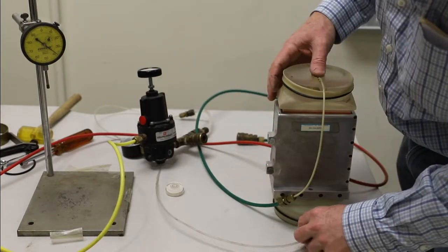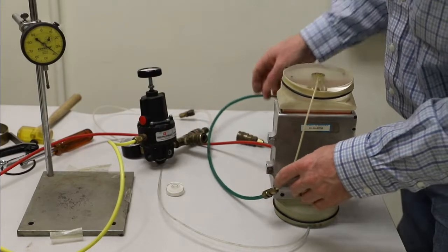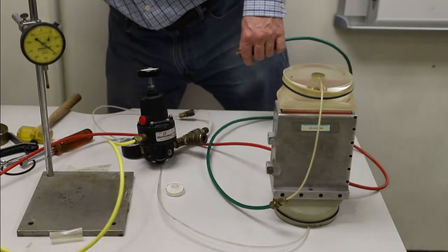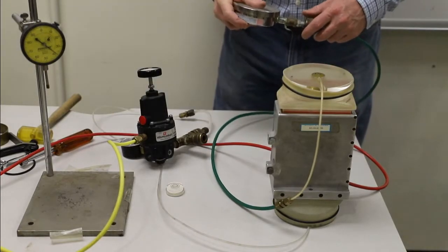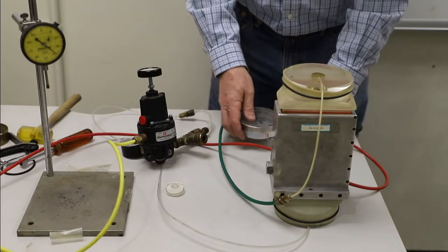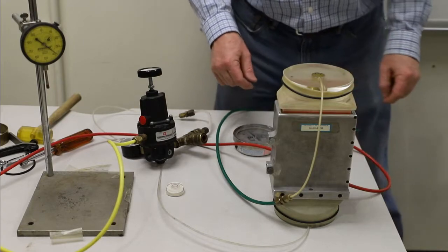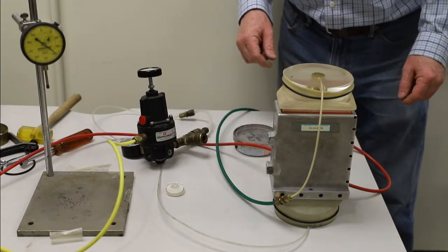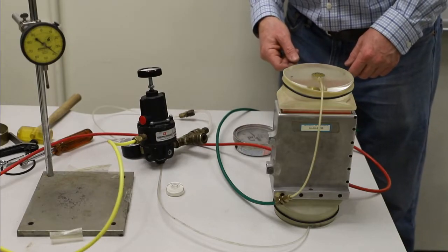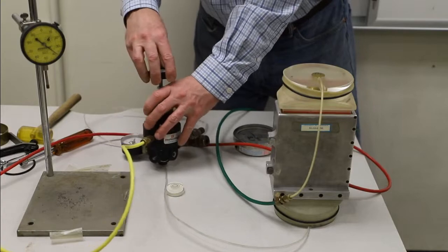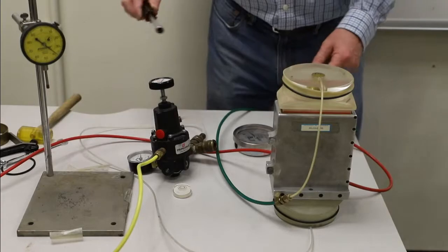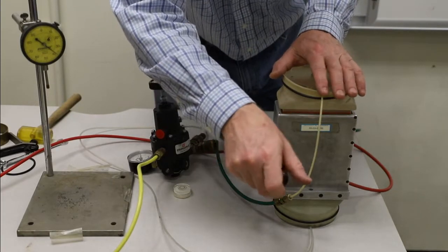And we also want to put a vacuum regulator into the end, coming out the top. Right? This is a superstition of mine. These samples are more prone to leakage than the triaxial samples. There's so many more corners and things involved. So now that we have vacuum on the inside of the specimen, we can take the mold apart and see how it's looking.